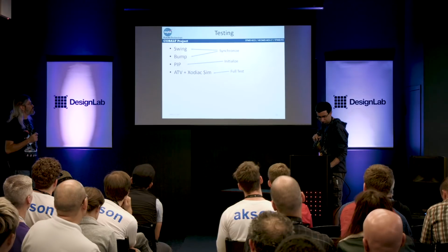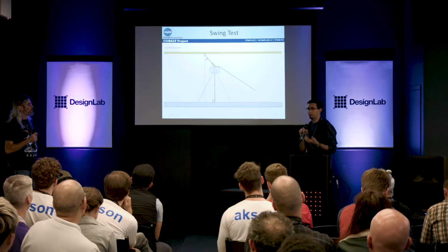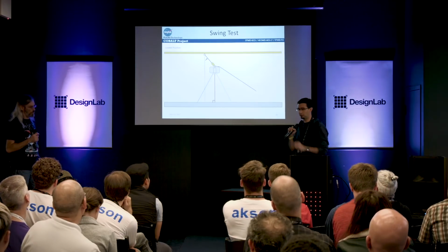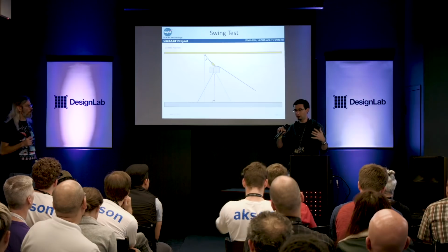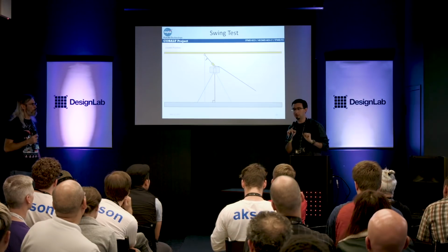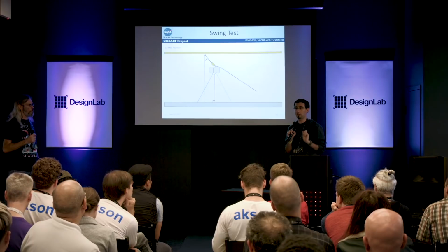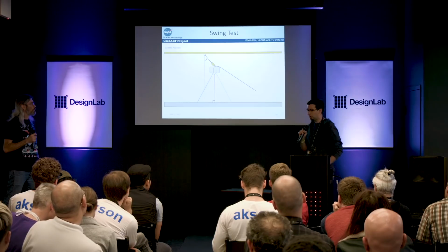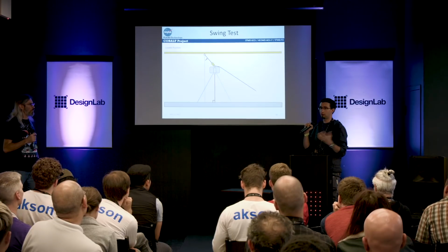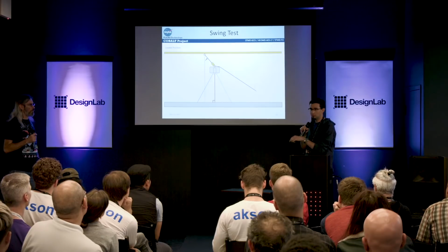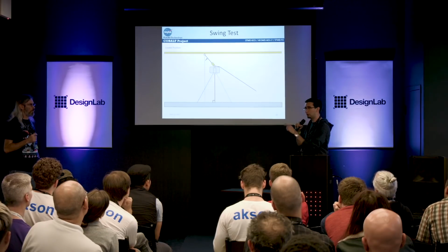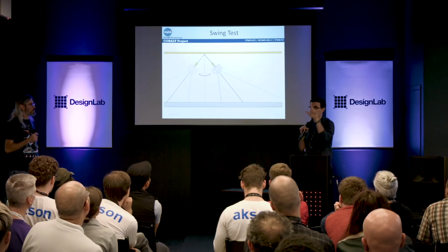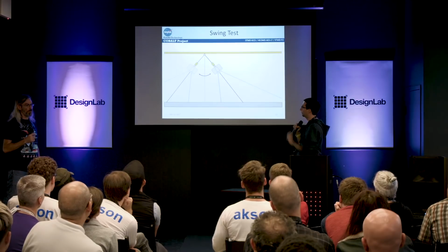So you have a newly built LiDAR by Langley Research that's been integrated into your payload, and you have your lander vision system that was developed at JPL. Now you have to mesh these two sensors together, and knowing the phasing between these sensors is very, very important: when the sensor measurement is taken and when it's being processed. So we thought, well, we could put this giant payload on a crane and swing it around, and the laser beams would see the ground get closer and further and closer and further and make a nice little sine wave, right? And appropriately so, the IMU would also see a rotation rate that's in a nice little sine wave.